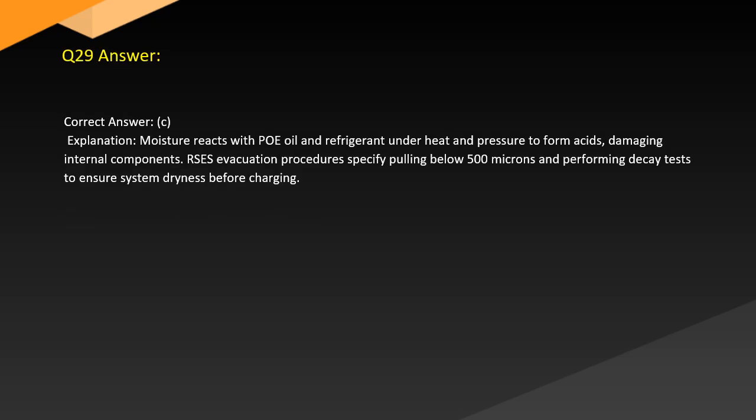Answer. Correct answer: C. Explanation: Moisture reacts with oil and refrigerant under heat and pressure to form acids, damaging internal components. RSES evacuation procedures specify pulling below 500 microns and performing decay tests to ensure system dryness before charging.